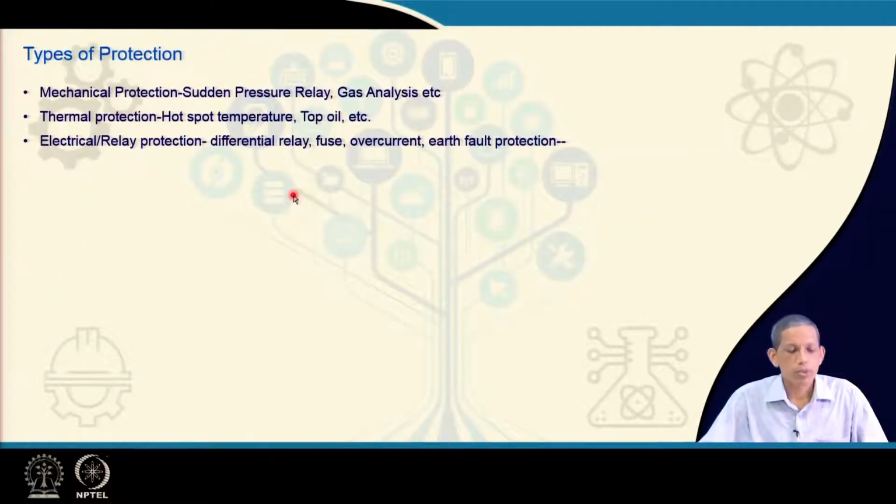Now, protection can also be divided into three categories: mechanical, thermal and electrical perspective. Pressure relay, gas analyzer, thermal protection, hot spot temperature, top oil temperature and so on, that is about the thermal perspective.